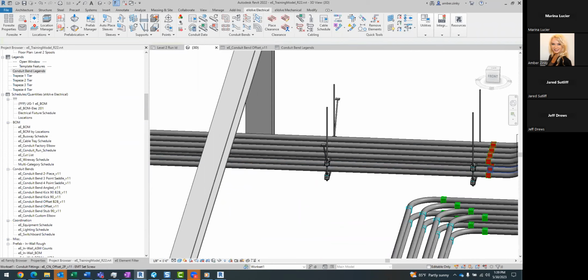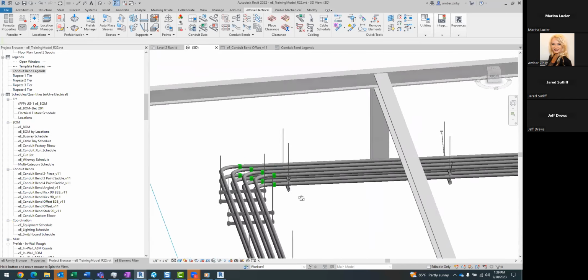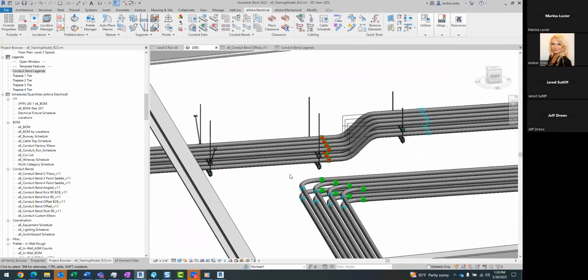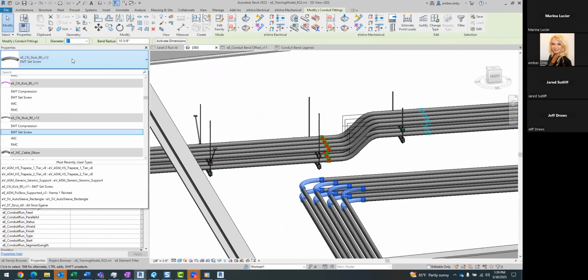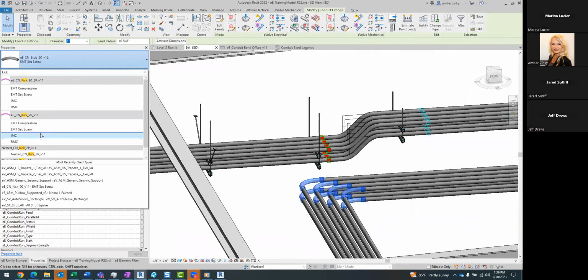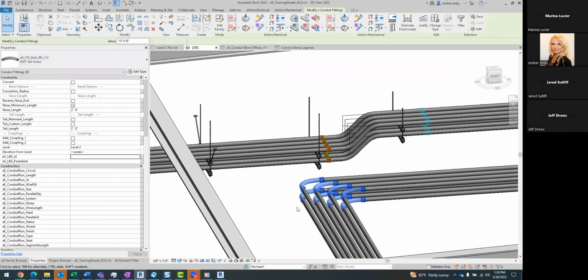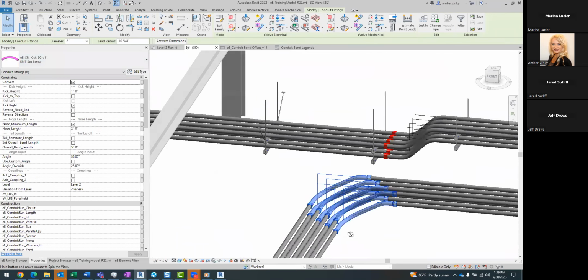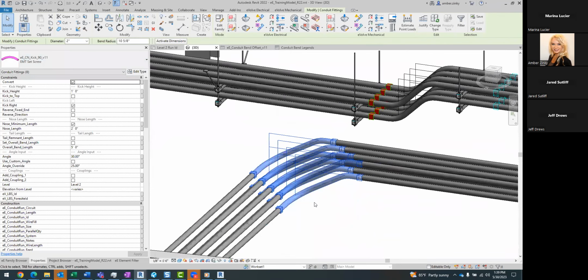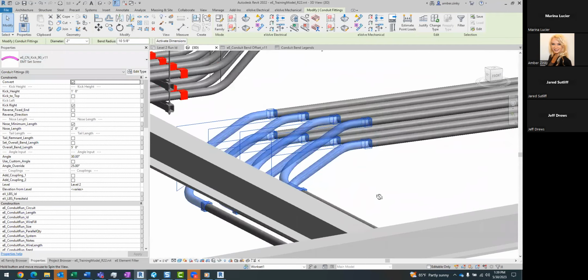Another thing as well is knowing Navisworks and just being able to fly around and utilize the program, even if you're not in a coordination project per se. If you have the architectural, structural, you can put in any one of your mechanical, electrical, plumbing, HVAC into the structural and architectural model within Navisworks and be able to fly around and very easily identify any conflicts with structural, architectural, and see that a lot easier than you can in Revit by moving section boxes or anything like that.